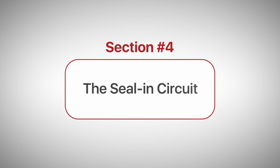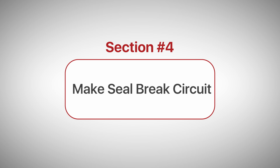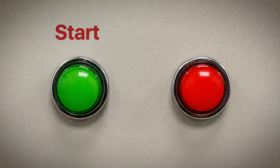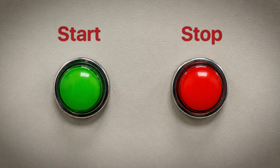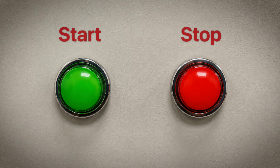Next, let's talk about the classic seal-in circuit, sometimes called a motor start-stop circuit, or what I like to call it is a make, seal, break circuit. Basically, the functionality is you've got a momentary push button to start it and a momentary push button to stop it. When you push that start button, it starts the motor and it stays running even when you let your hand off. And then when you're ready to stop it, you push the stop button and it turns off.